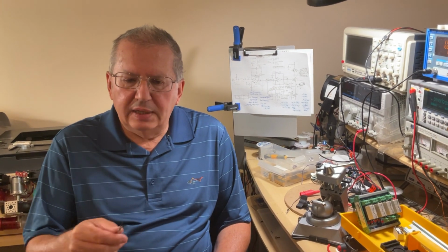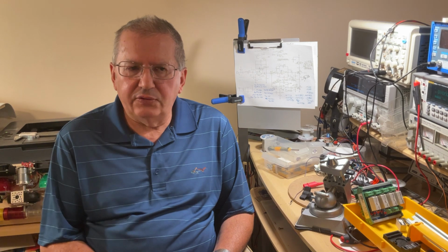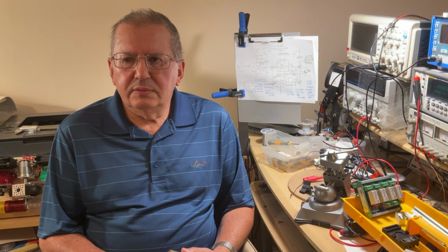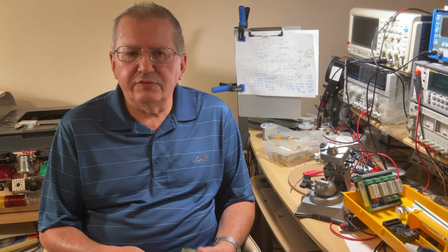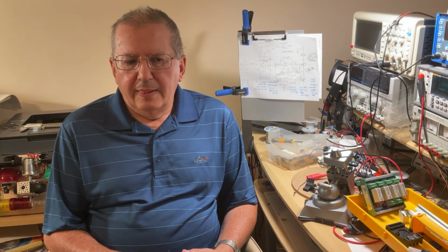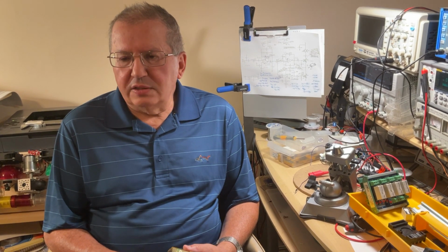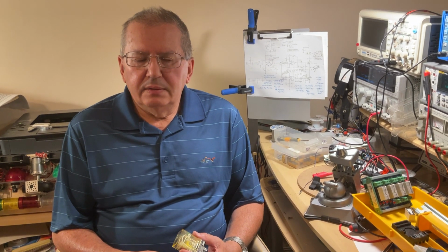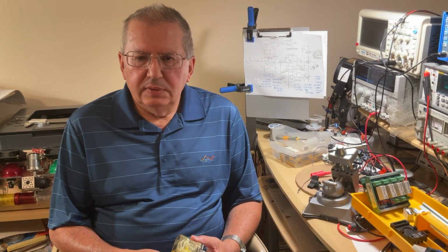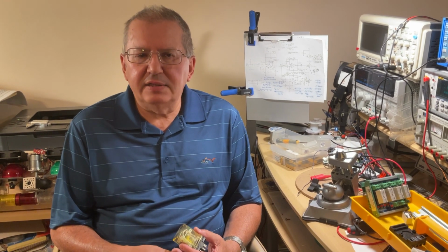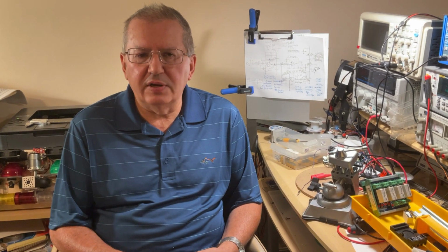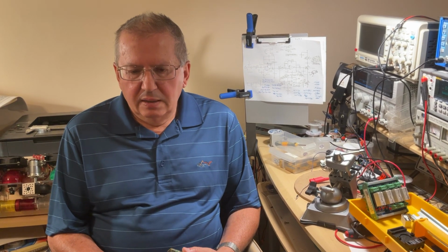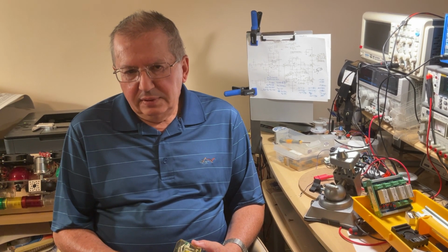So then I've made a short list of electrically controlled switches. Why then do we talk about the relays? What is the advantage of the relay over the other ones? Again, simply put, the transistor, which is the most common electronic switch, cannot deal with AC loads. Even if it can amplify AC signals, like it happens in all the sound amplifiers everybody uses, the load is not an AC one. The TRIAC can take an AC load,